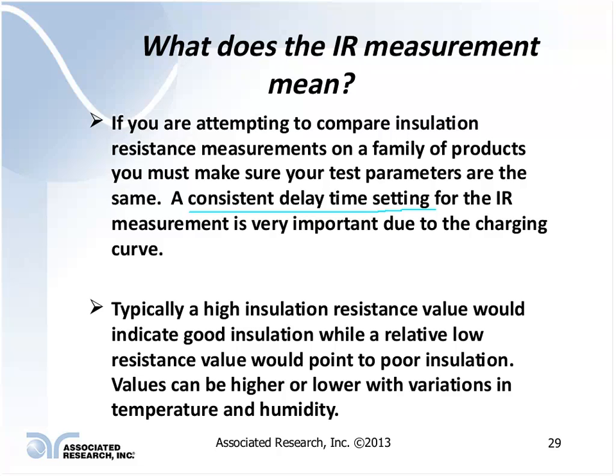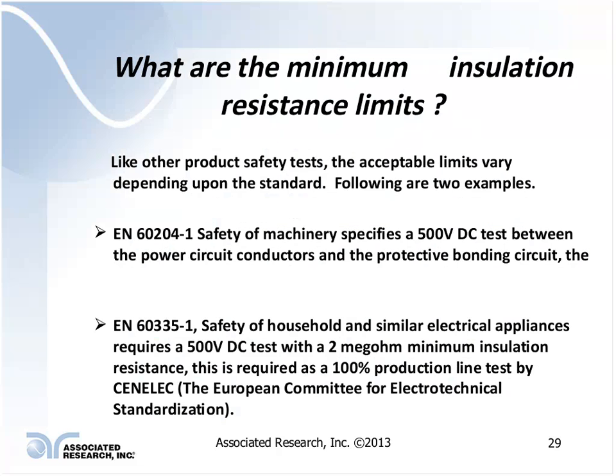It's been a long time since I've looked at it, and I'm not even going to guess. I don't recall what the number was offhand. But typically, high insulation resistance values indicate good insulation, while relatively low insulation values point to relatively poor insulation. These values can vary based upon temperature and humidity.